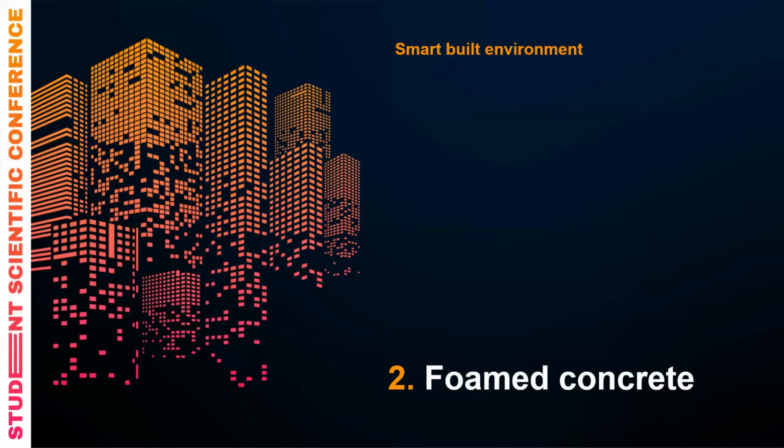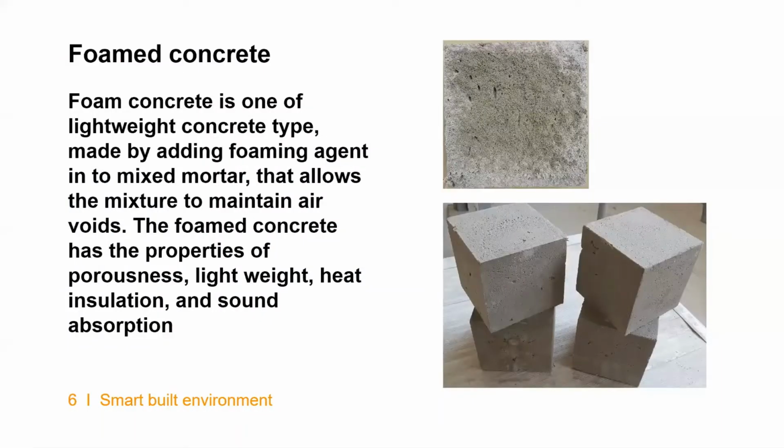So, my topic: I'm making lightweight concrete, so foam concrete. Foam concrete is one of the lightweight concrete types. It's made by adding foam agent into mixed mortar that allows the mixture to maintain air voids. Foam concrete has the properties of porousness, lightweight, heat insulation, and sound absorption.